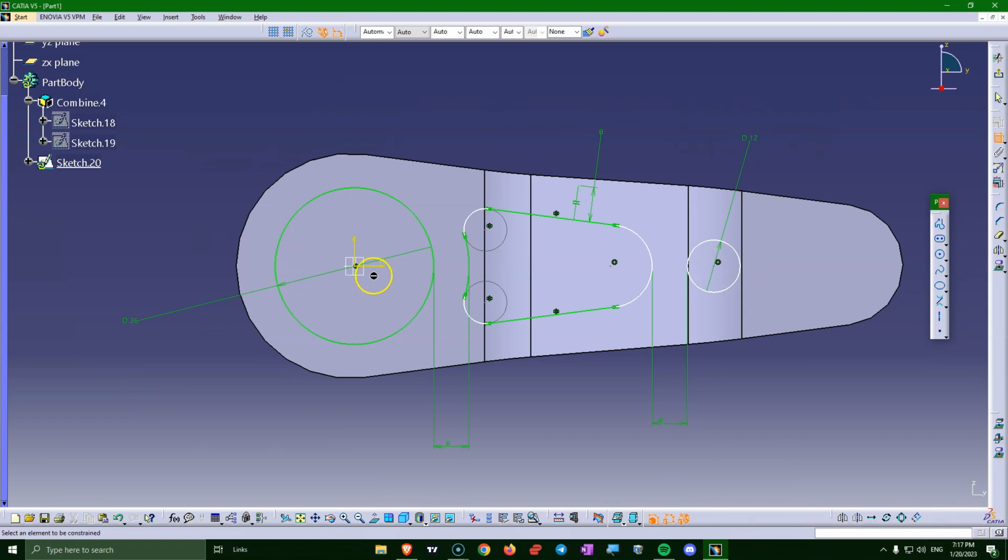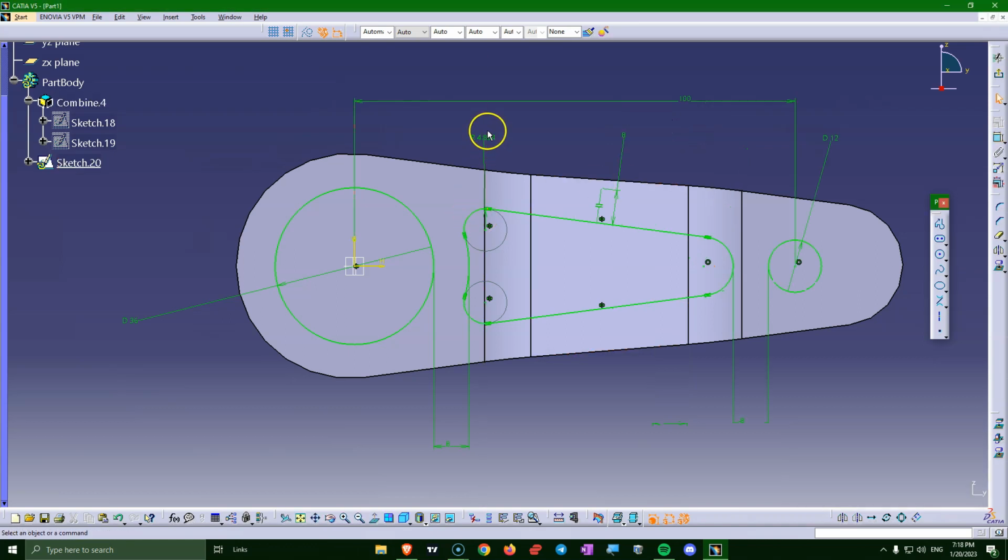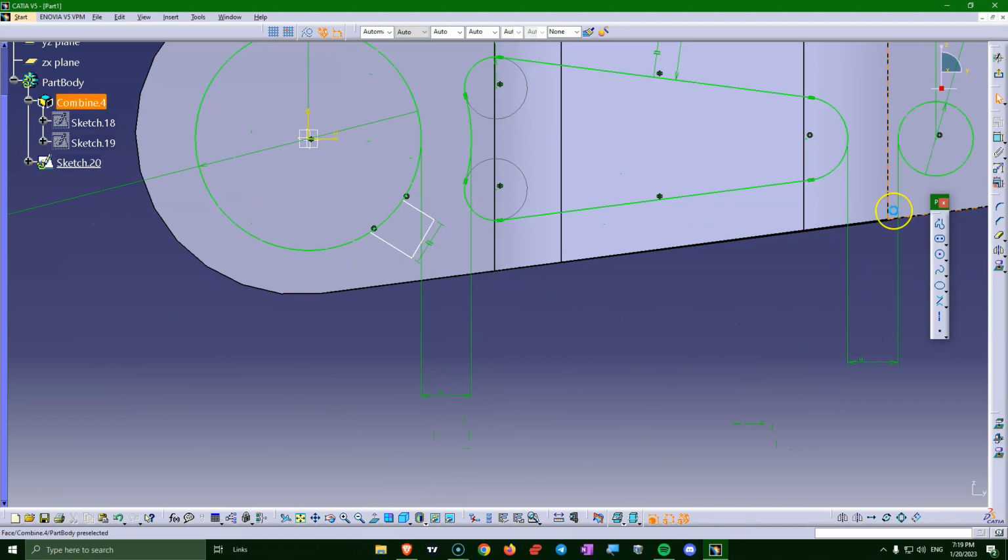and from this point to the vertical axis here, this is going to be 100, and this circle here is going to be 5. And here let's design a dent. So I want to make sure that it doesn't take any constraints around here. So the only one acceptable will be parallelism between this line and this line. And then I want 90 degrees between this one and this one, so that's perpendicular. The same here, this is perpendicular.